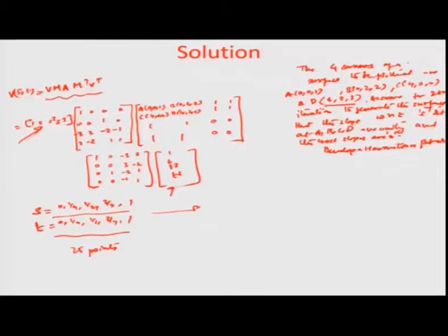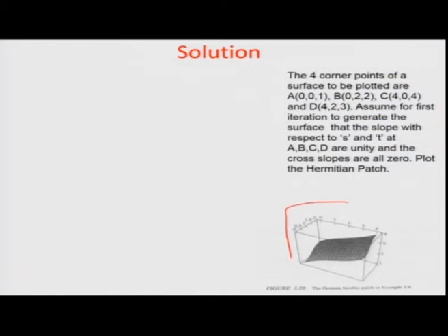So, I am not going to actually show you how I did these MATLAB oriented computations, but if I wanted to look at how the plot of the surface would look like, it typically looks something like this, okay, which we are considering. Here probably we took a little more than just 5 different points. You could take points in the extent of, let us say, 0.1 or 0.2 to resolve the surface very well. And so, you can see a 3-dimensional surface patch getting generated, which has variation along 2 independent variables in the s and the t direction, okay, and a certain value of the z based on whatever are these s and the t values at a certain point.